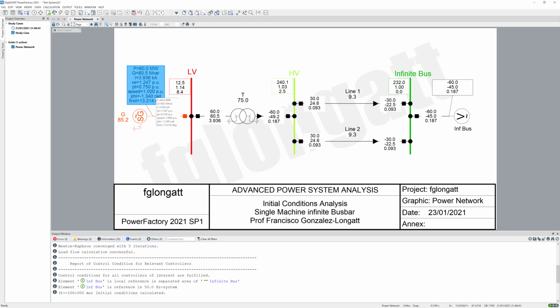You need to think and be sure about what you are doing, because there are many angles that can be calculated inside DIgSILENT PowerFactory, and every single one of those angles has an application, okay? For that reason, you go here to the user manual, and there is the technical reference for the models, okay?